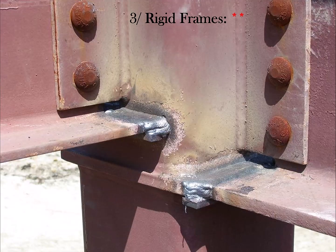Rigid frames, you look at this maybe kind of semi-ugly weld. It's not a bad weld, but structurally, how pretty the weld is is not so important. What matters is that the weld is a deep penetration between the two metals. Oftentimes structural steel buildings will take steel members, beams, and columns, and bolt them together initially, and then you'll come back for at least some of the joints like this and weld them, a deep penetration weld, top and bottom of the I-beam, for sure. We'll look at structural steel later on in this course, in the last quarter of this course.